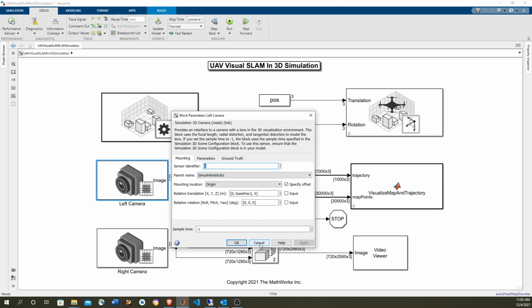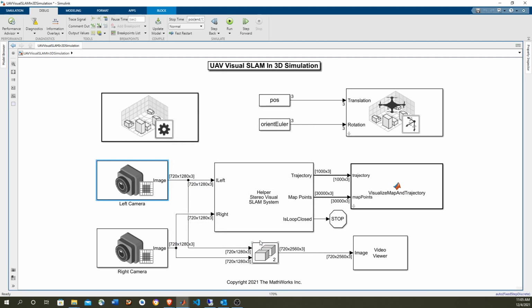Stereo vision is very effective for the SLAM algorithm because for each snapshot, for each frame, you can triangulate using a disparity map between the distance between the points of the two views. We can triangulate them and get the three-dimensional points for each frame. So it's way more precise than monocular vision.